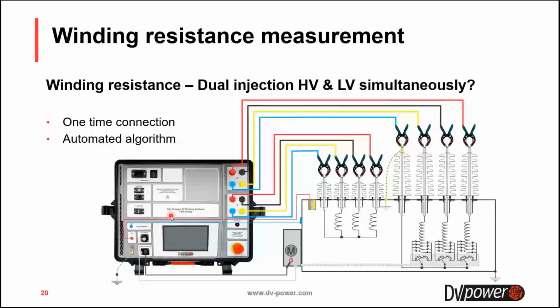With the three-phase units, measurements of all types of transformers are much easier because the operator does not need to know many things. He must only recognize the vector group on the transformer and set the testing parameters with it.